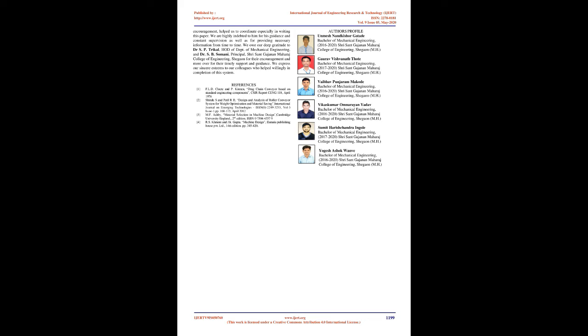4. Stress analysis. From stress analysis of a component we can study and see the stress distribution over the component surface due to the forces acting on it, which is not possible to find theoretically. 5. Displacement analysis. From displacement analysis we can study the deformation of the component due to the force acting on it. 6. Factor of safety. From this analysis we can study the ability of a system's structural capacity to hold beyond its expected or actual loads.